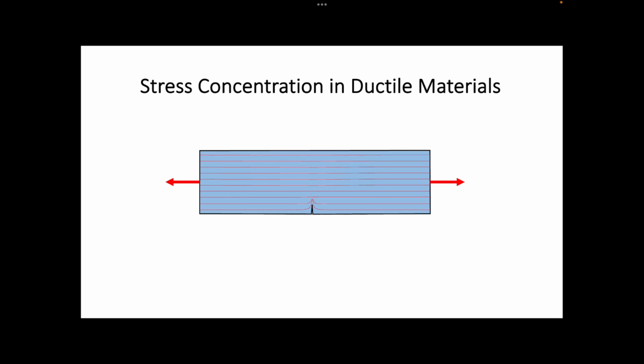To finish our discussion of this topic, stress concentration is often not an issue with members made of ductile materials. The reason is there can be a redistribution of stress to the surrounding material due to yielding if a point within the body is subjected to stress concentration.